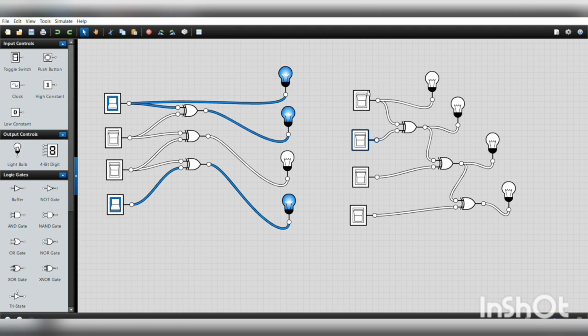So next, coming to gray code to binary code conversion. If we give the inputs as 0, your binary output is always 0. If you give the gray code input as 0, 0, 0, 1, your binary code output is 0, 0, 0, 1. If you give some other inputs like 0, 1, 1, 1, your corresponding binary output becomes 0, 1, 0, 1. And if you give all inputs as 1, you get the output as 1, 0, 1, 0.